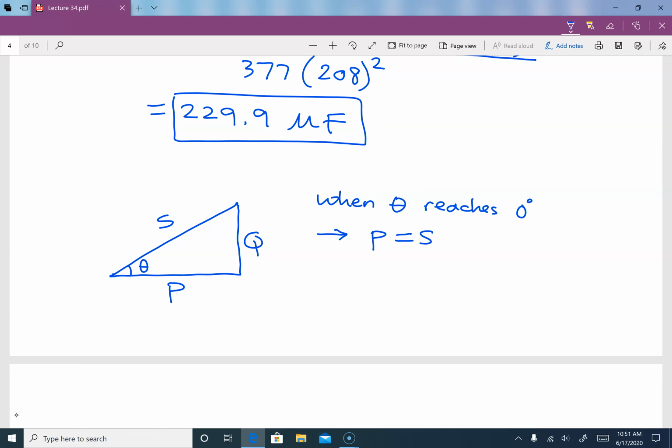So usually the power utility companies, not only here in United States, but everywhere in the world, when they send the bill, they send that bill as kilowatt hour. Since the P is in kilowatt and the energy in kilowatt hour, they are claiming that they are charging you for this P, while honestly they are charging you for this S. Okay, so they are charging you for S.